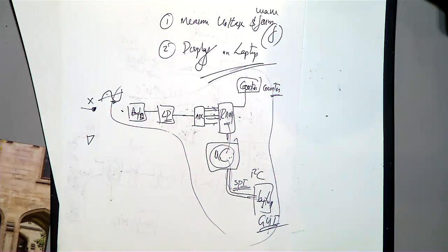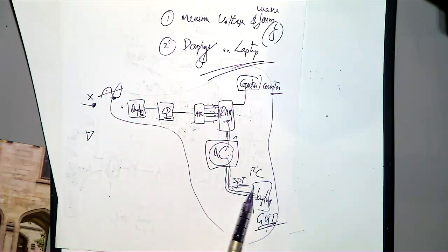But when it comes to oscilloscope, now this is just designing, but if you do like this, it will randomly display some waveforms. It will not be like your oscilloscope, where neat waveforms are coming continuously, because here one thing is lacking, that is called a trigger function. If you don't have the trigger function, all the signals will be randomly displayed. So we are missing so many blocks in the oscilloscope. So we will be introducing blocks one by one.